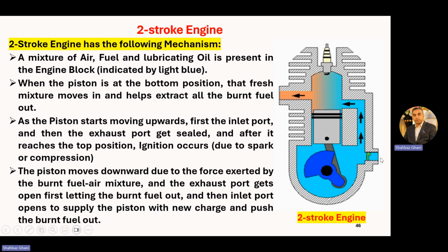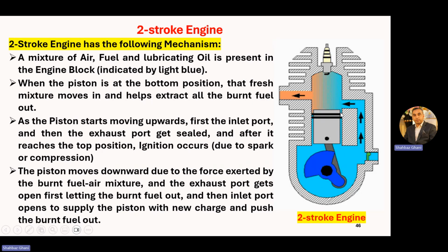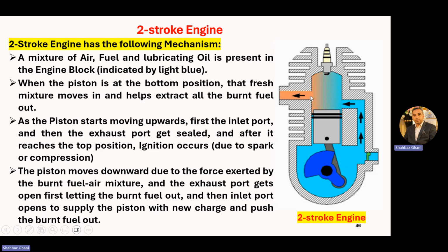So air fuel is in crankcase compression. Air fuel mixture is mixing in. When the piston is at the bottom position, that fresh mixture moves in and helps extract all burnt fuel. Now, piston is at the bottom, the air fuel mixture is coming in. As the piston starts moving upward, first the inlet port, this is your inlet port, and then the exhaust port sealed. This is your exhaust port.